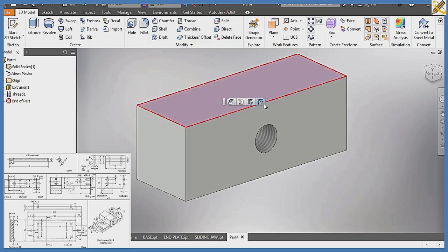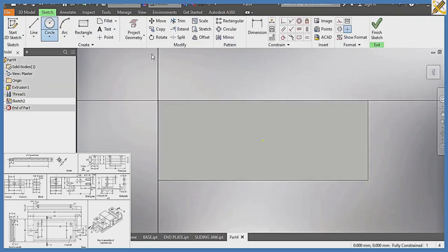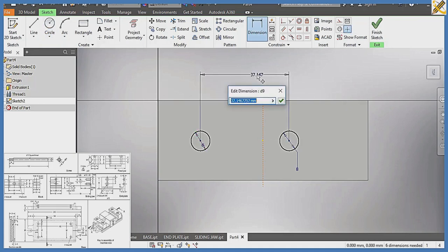Right after that, I'm going to pick the plane, create that sketch right there. So I'm going to pick a line in this manner, hidden line. Okay, hidden line, then roll it through the midpoint right there, then escape, negate the hidden line, then pick my circle. We have 2 holes of diameter 8, so locating the midpoint right there. The first one 8, enter. All right, the second one 8, enter. So the distance between these 2 circles is 50. All right, yeah, this is 50 if I am correct, absolutely correct.